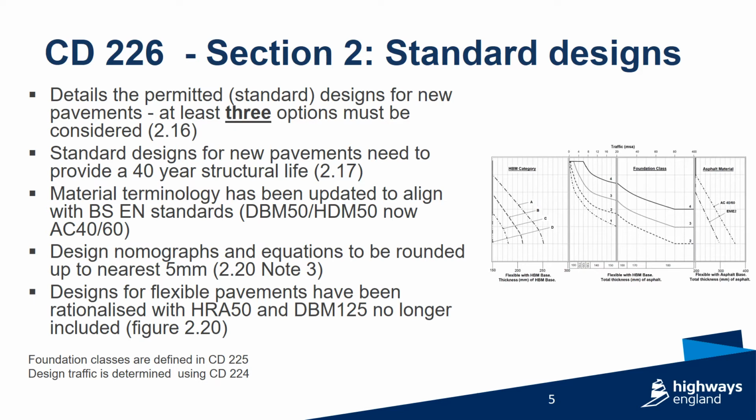You will see in Figure 2.20 that the design curves for flexible pavements have been rationalised, with HRA 50 and DBM 125 no longer included. The primary reason for removal of these mixtures is that they are more prone to deformation under heavy traffic loading.